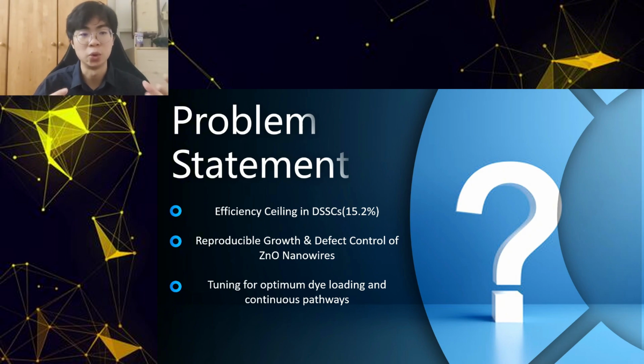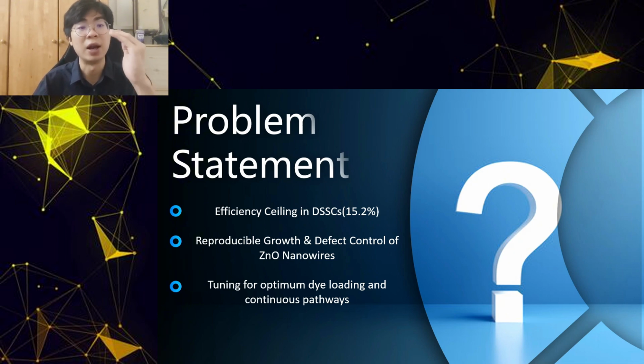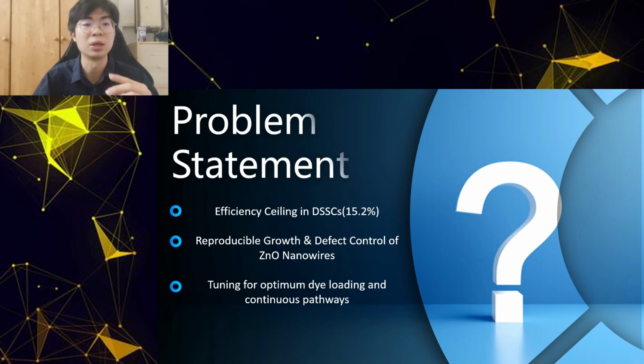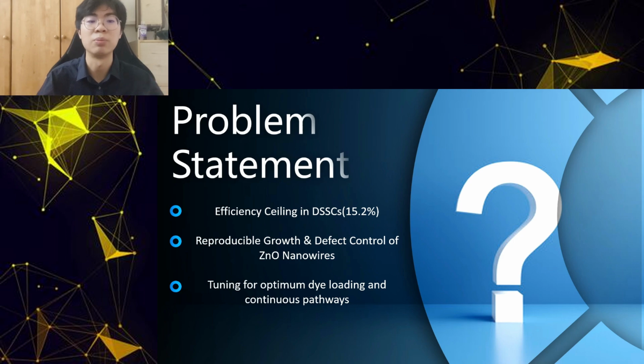Thus, fine-tuning the aluminium atomic percentage in aluminium-doped zinc oxide nanowire is crucial for achieving the above and maximizing the performance. Most research papers cover 0.5, 1, 2, and 3 atomic percent of aluminium, and have found that 1 atomic percent shows the optimum zinc oxide nanowire properties. Hence, in this research work, the investigation of aluminium doping will be centered around 1 atomic percent of aluminium for fine-tuning. The purpose of fine-tuning is to discover a new process-structure relationship and the sweet spot for the maximum electrical and optical properties of aluminium-doped zinc oxide nanowire in DSSC.